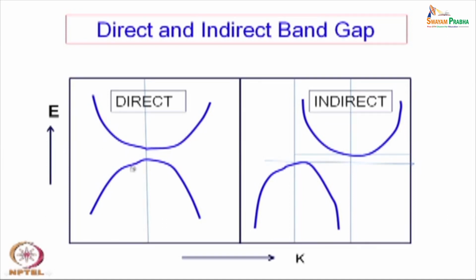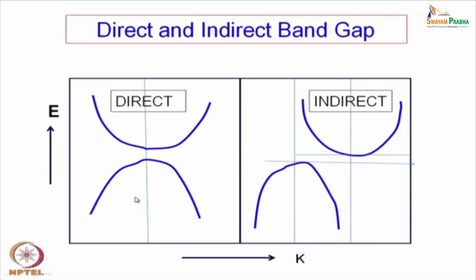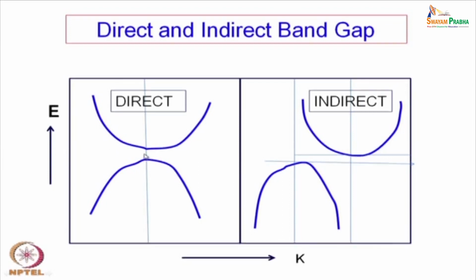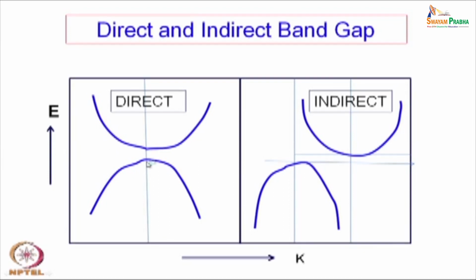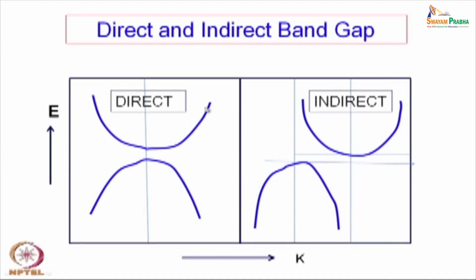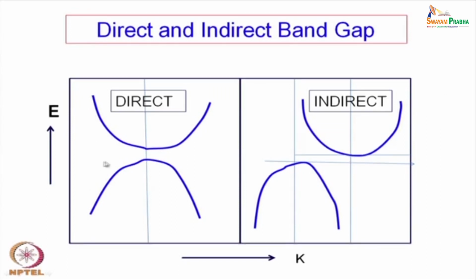Okay. So, along this direction the gap is more, as you go from this to the right or the left, the gap is increasing, but the minimum gap may be somewhere here. When we define the band gap or forbidden energy levels, we will always talk about the minimum gap. These are two different surfaces, this is one Brillouin zone, this is another Brillouin zone.